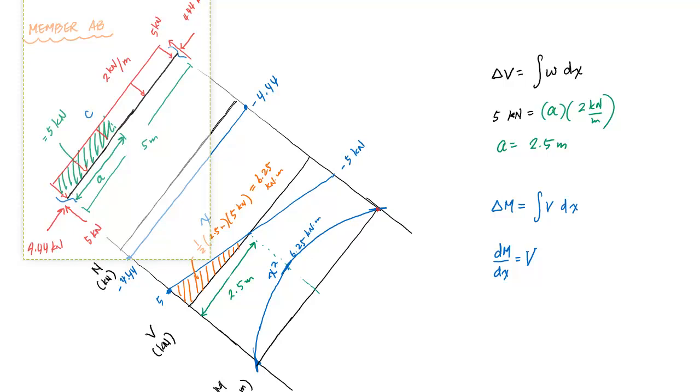If I sum the forces in the quote-unquote horizontal, or in the direction parallel to the normal forces, you'll notice the member is also in equilibrium. And that's also true. So whenever I cut out a member, the member itself must also be in equilibrium. And so I could have determined these end internal loads at point B just from doing equilibrium of the whole member, as opposed to drawing the shear and moment diagrams, if I wanted just that point.